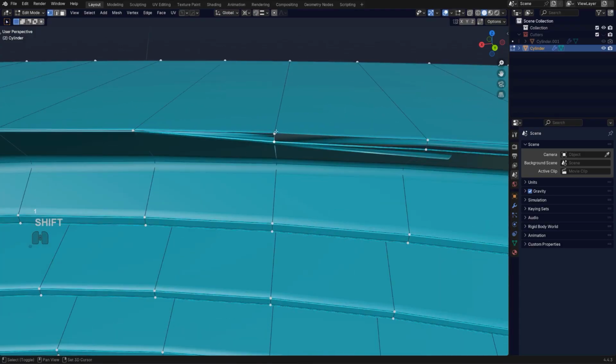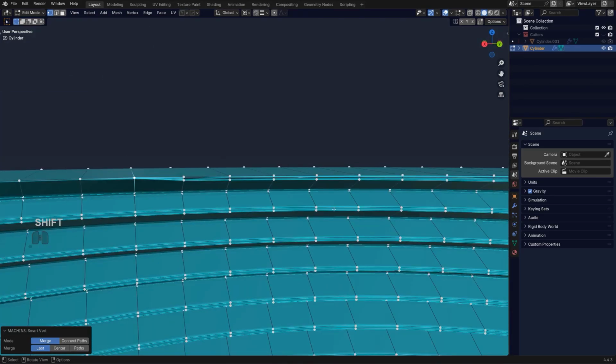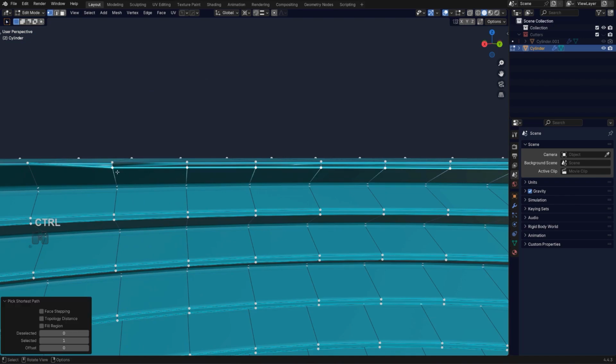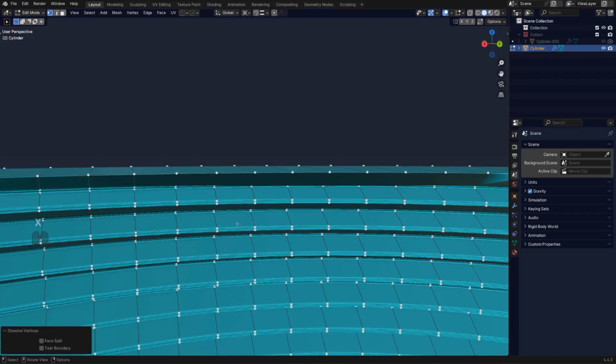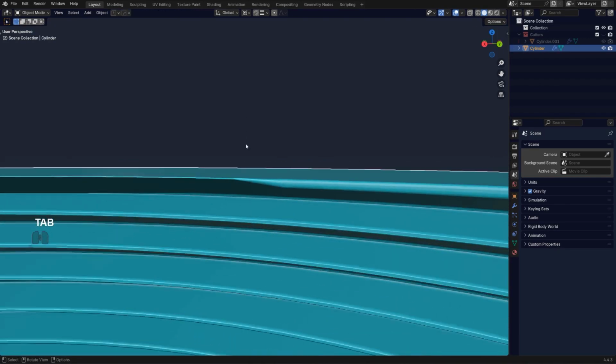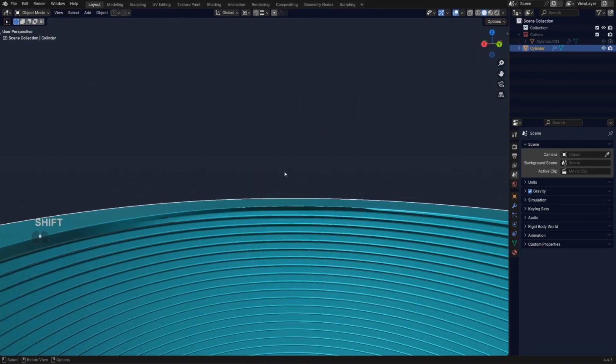So it's just too big for it, you know what I mean? See, like stops here, so let's just grab these and dissolve them. So dissolve verts, and then what we can do is do this. It should be fine. There we go. So that will work.